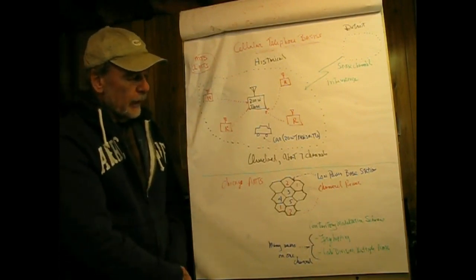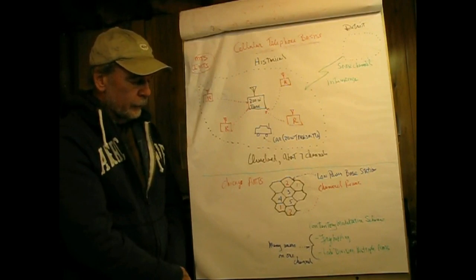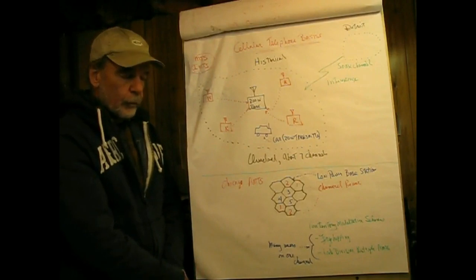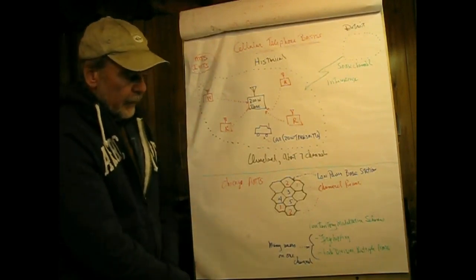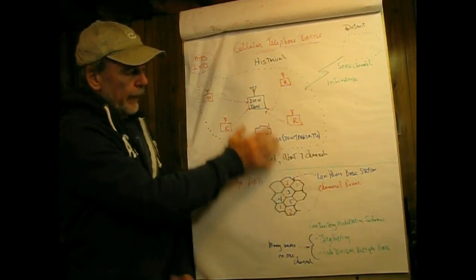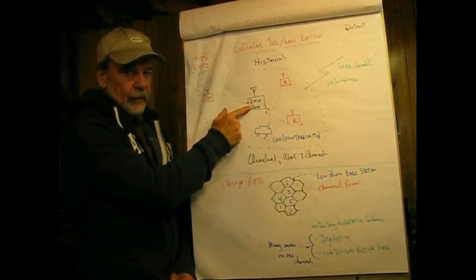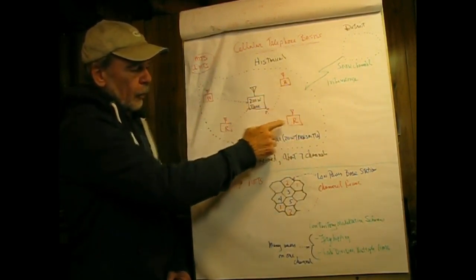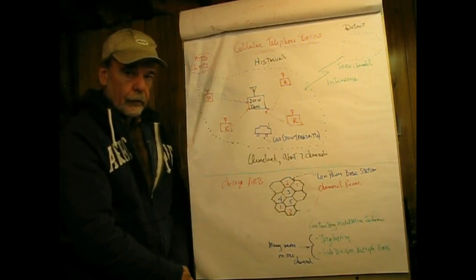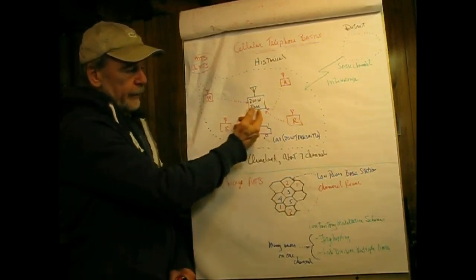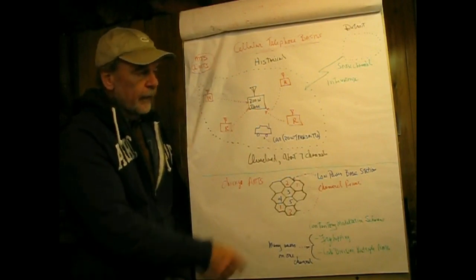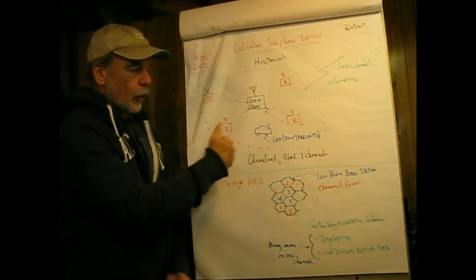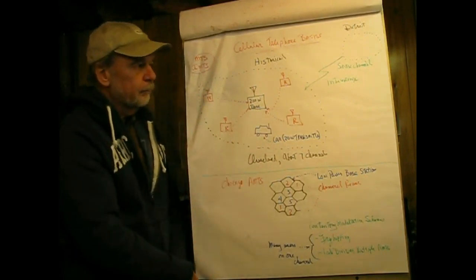So in Chicago, a new and improved system was trialed and went into service about 1984, and this was called AMTS, or Advanced Mobile Telephone Service, and it's based on cellular technology. Now, if we go back up to here, what we have is a 200-watt base station which basically can cover all of Cleveland. And located in the suburbs and downtown, there would be satellite receivers. These receivers would connect into the electronics associated with the base station and select the least noisy signal to be the one that is passed along to the person on the telephone network.